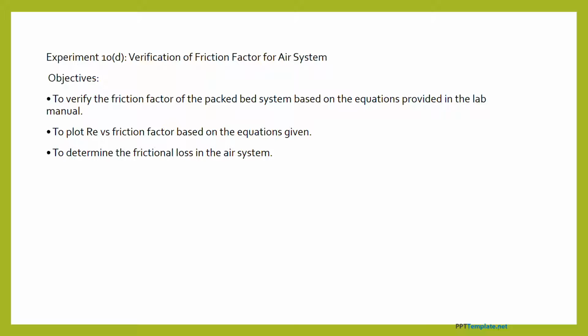So we don't need to do the experiment, but the objective of this experiment is to verify the friction factor of the packed bed system based on the equation provided in the lab manual, to plot the Reynolds number versus friction factor based on the Ergun equation, and also to determine the frictional loss in the air system.